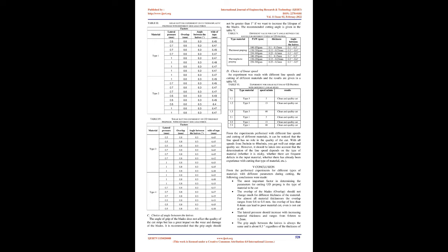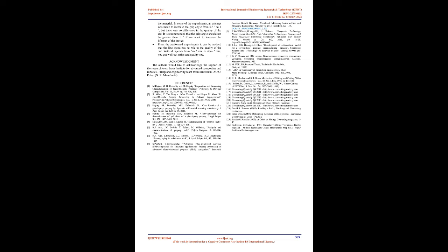C. Choice of angle between the knives. The angle of grip of the blades does not affect the quality of the cut strips but has a great impact on the wear and damage of the blades. It is recommended that the grip angle should not be greater than 1 degree if we want to increase the lifespan of the blades. The recommended cutting angle is given in table 5.